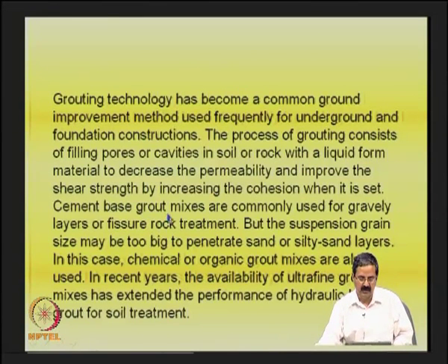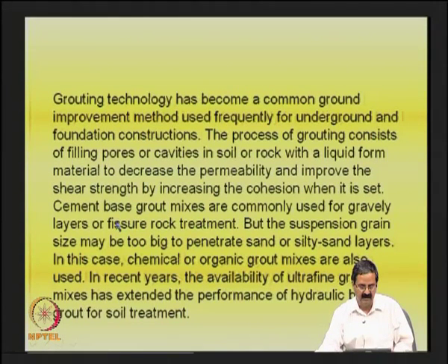Cement based grout mixes are commonly used for gravelly layers or fissure rock treatment, but the suspension grain size may be too big to penetrate sand or silty sand layers. In many cases, when you put the grout material, the particle size is very important. Whatever you are trying to grout, it should get into the soil system and stabilize the whole area.